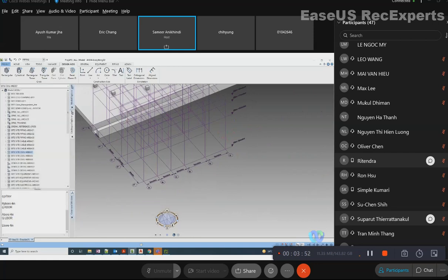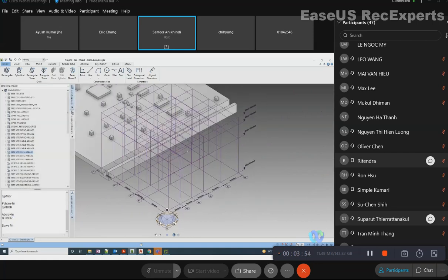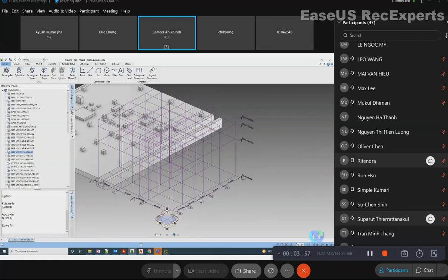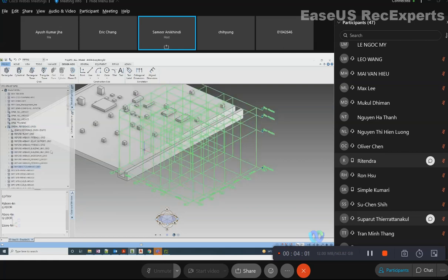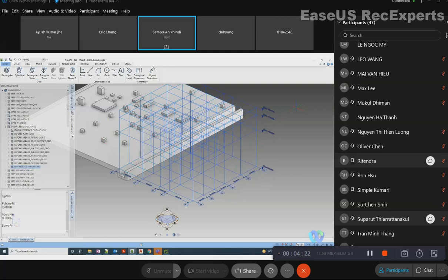But for now, you can try this by yourself, making a grid by yourself. If you click this grid, it will show this under the grid world, CTCI area 01 grid. Please try, take 5 minutes to make this grid. You have to start from design aids, rectangular grid. Take some reference of the model like civil area 01 and start from there, because you will have difficulty in viewing it. And I will open the floor for question in next 5 minutes.